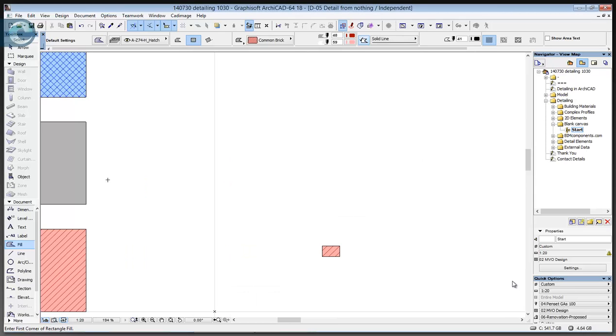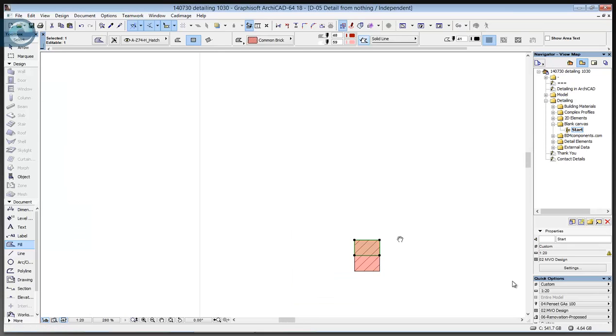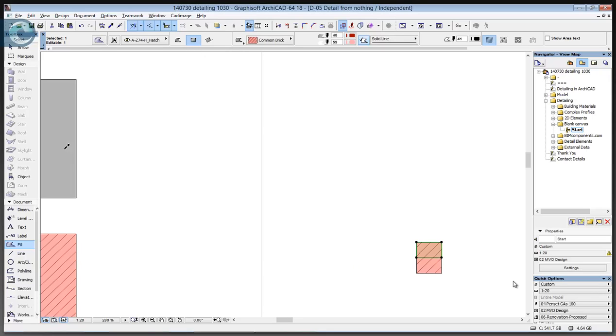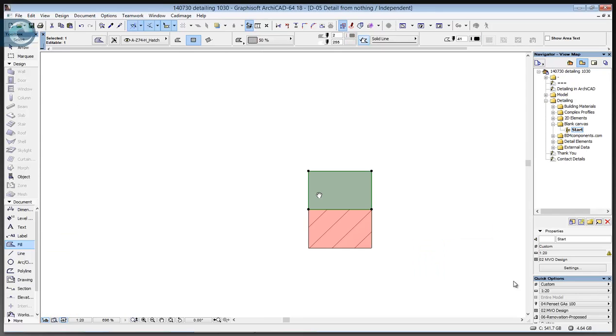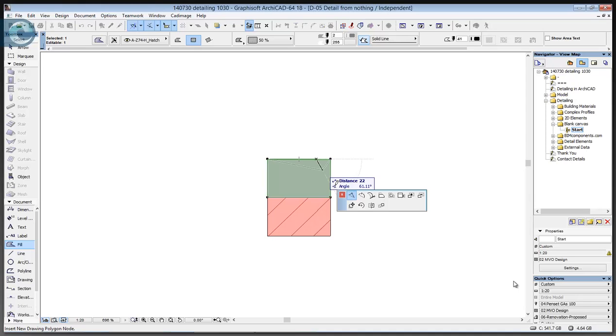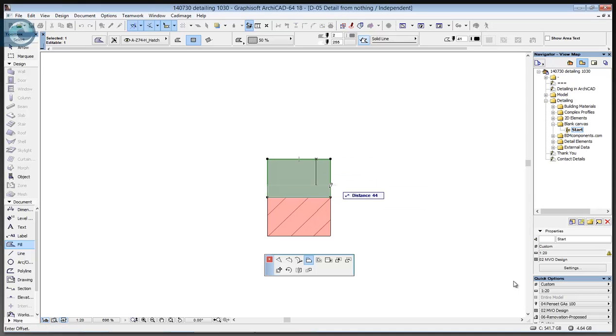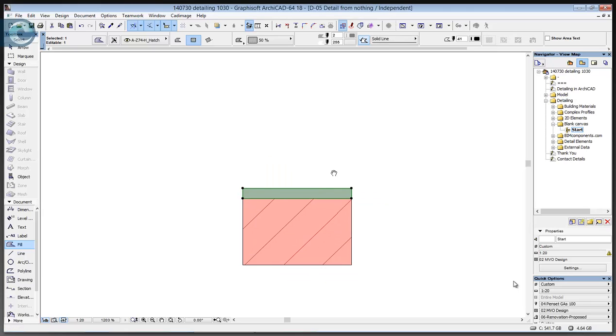I'll then add some mortar on top of that. In fact, let's just keep it like this first. Let's just copy it directly on top of itself, one on top of the other. And then because I've used these swatches, I can Alt-click to pick up, and Alt-Command or Alt-Control to inject. And that converts from brick, obviously, into a piece of mortar. And then we just shrink it down 55 mil, so we're left with a 10 mil band of mortar.